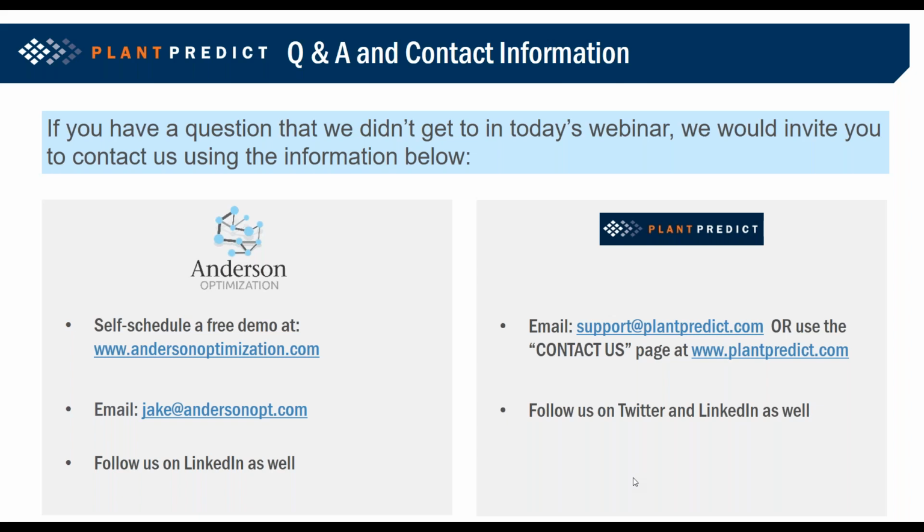was a little bit more conservative, as we've tried to be, because we're really concerned with how these simulation tools are modeling the bifacial backside gain, specifically in your winter months. And the study showed that most tools are around 5 to 10% over predicting. PlantPredict came in much less than that. So we were pretty happy with the results from that paper.